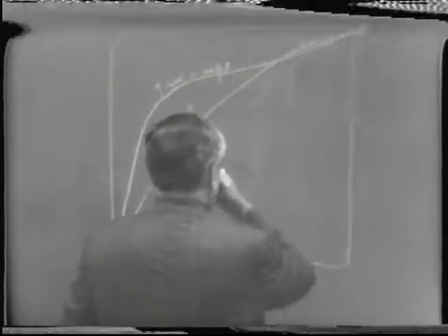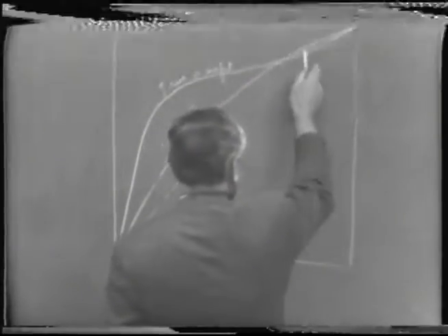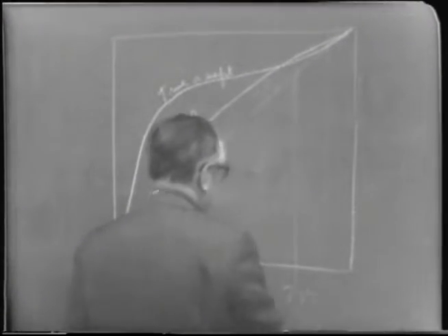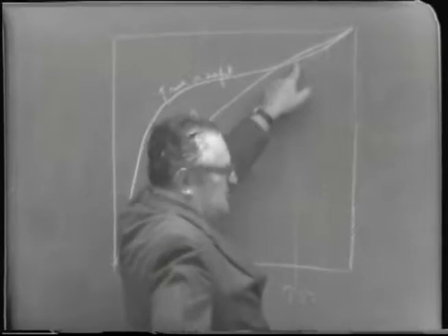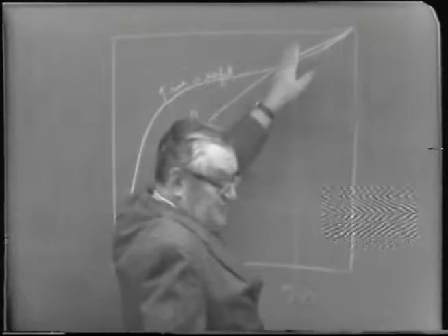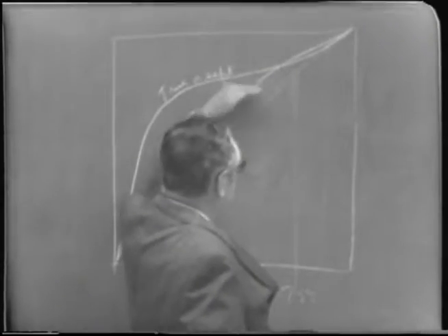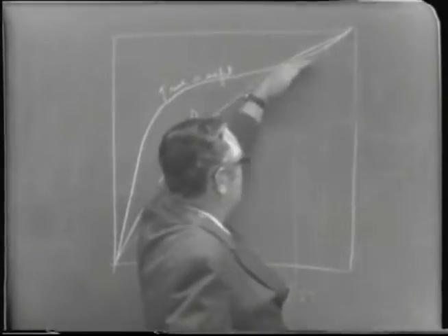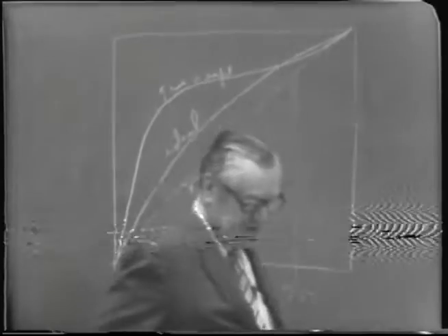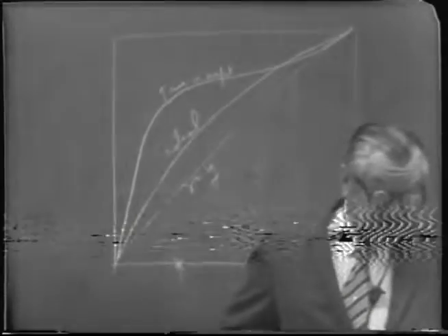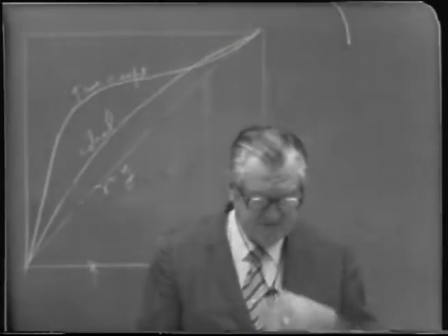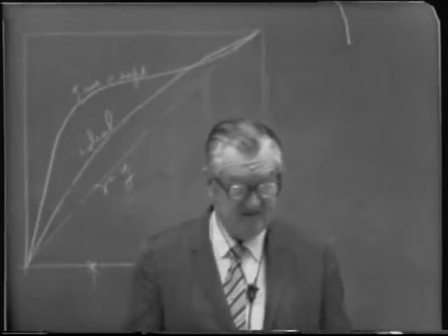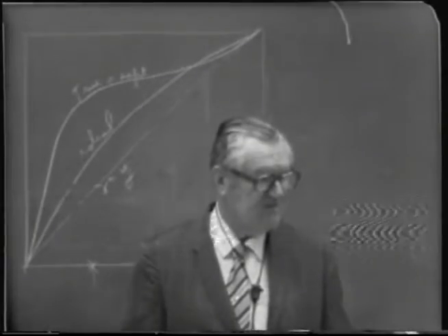On the other hand, and I guess I didn't draw this very well, but anyway, for a 75% mixture, the actual curve is below what would be for an ideal mixture. It's approaching the azeotrope here, almost tangentially. So at high alcohol concentrations, as represented by 75 mole percent, it's more difficult to separate alcohol from water than it would be if it were an ideal mixture.